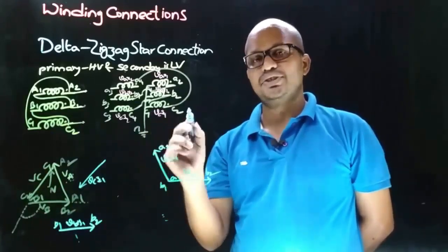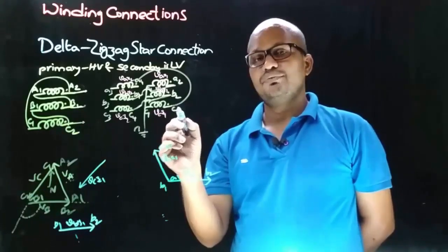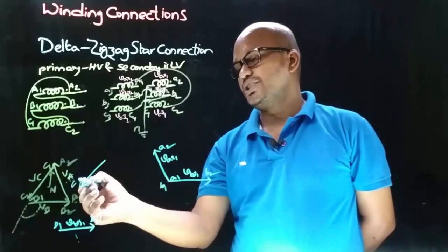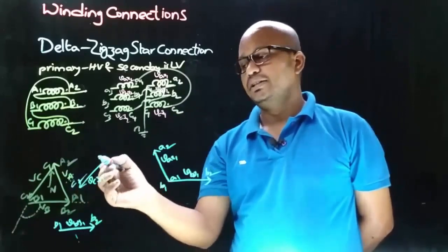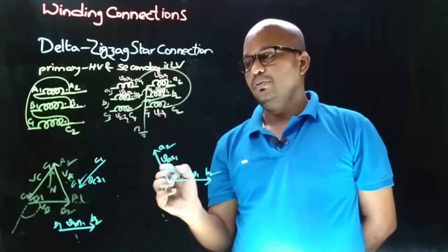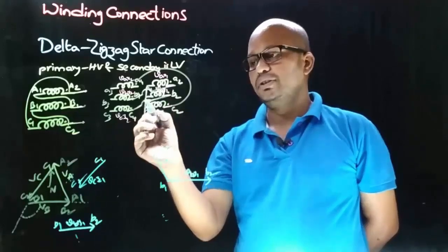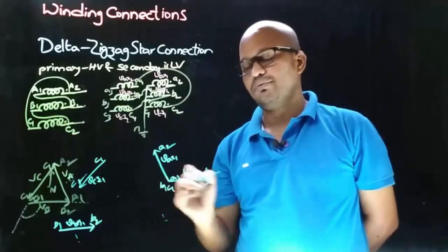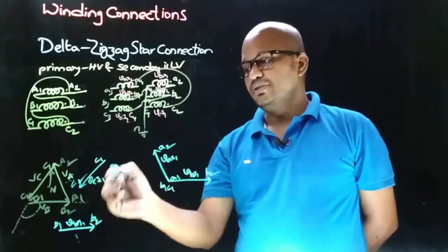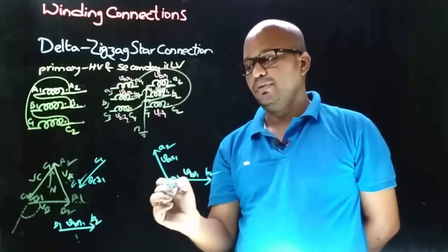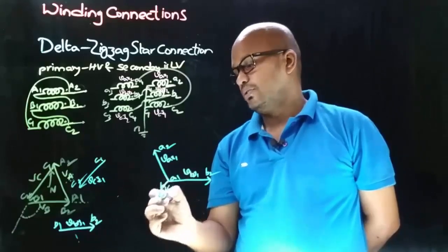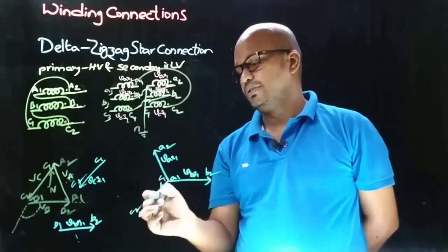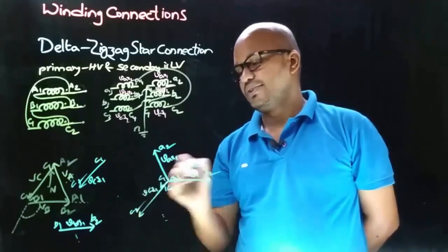Here the terminals are C1 and C2 and the connection is taken from the dot end terminal, that is C2. Therefore the arrow will point towards the connection we took from, that is C2, and the other end will be C1. Observing the winding connection, to A1 and B1 there is C1 connection, meaning in the phasor diagram to A1 and B1 there must be C1. Therefore draw this phasor diagram such that A1 and B1 will have C1. So like this. This is C2. This is C1. This is the VC-Z1 phasor.